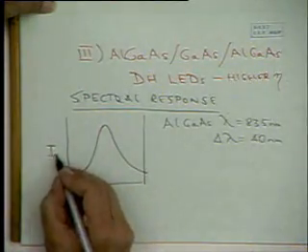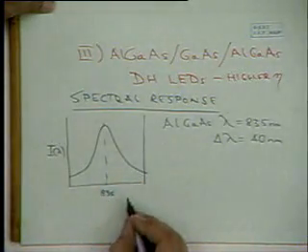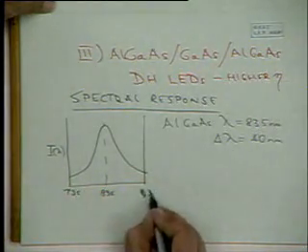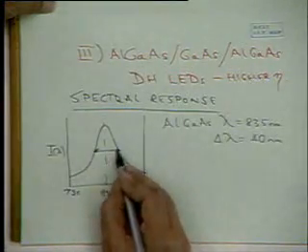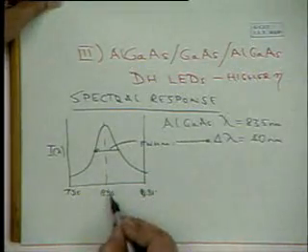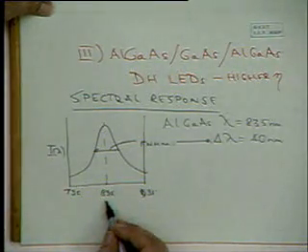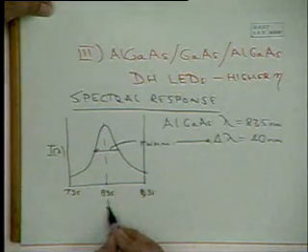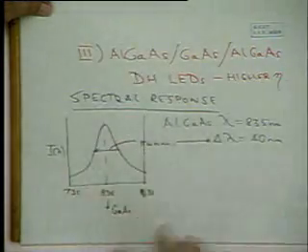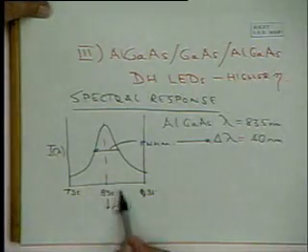This is the intensity as a function of lambda. Okay, this is the full width half maximum, and you can see the 835 corresponds almost to the band gap of gallium arsenide, right? So this is an AlGaAs LED in which the active layer is gallium arsenide. Okay, and the aluminum gallium arsenide forms the confining layers, right? Because 835 nanometers corresponds to about 1.4 eV.